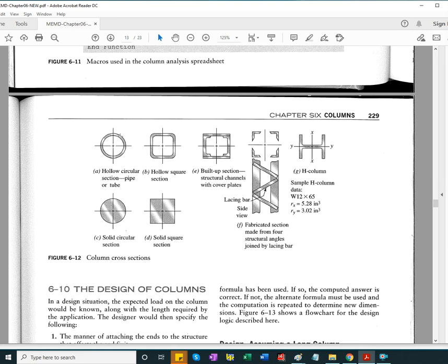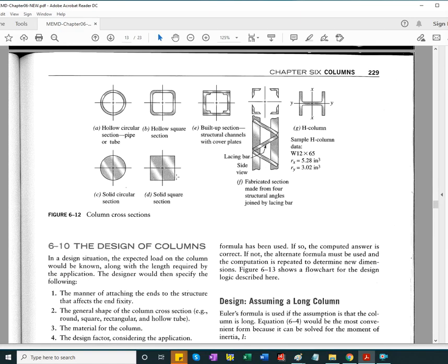And you can repeat the analysis and you get a cross section as you desire. Based on my experience working problems with students, identifying the correct end fixity coefficients is the problem there. And remember, there are theoretical values and there are practical values. And then the end fixity coefficient can differ in one plane versus the transverse plane, and you will have to do the analysis for both.